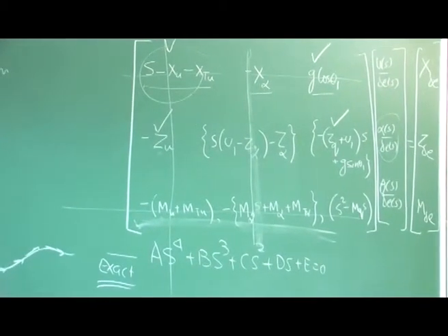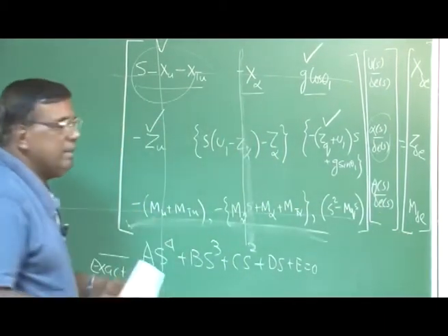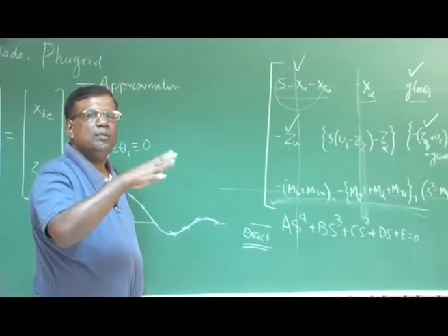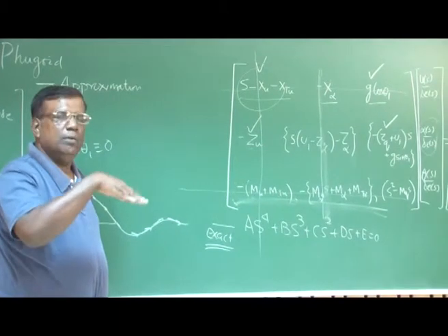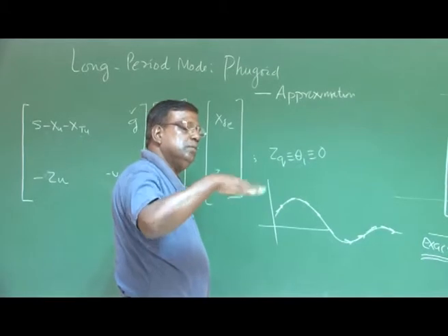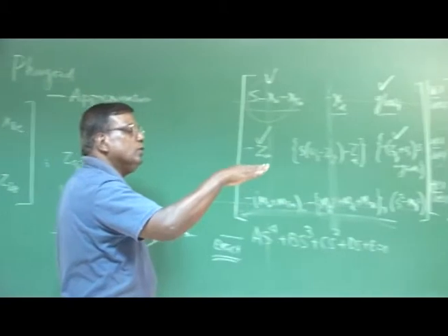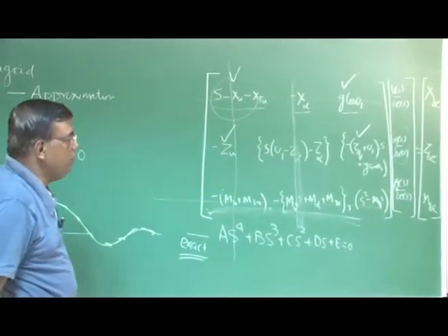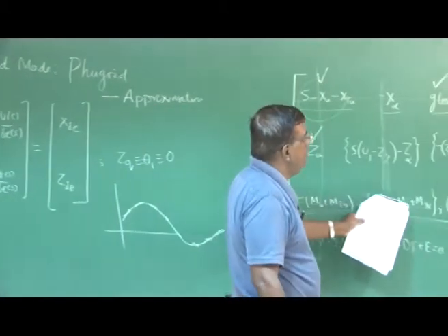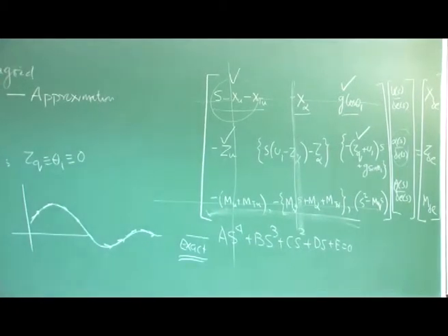Second thing, the third equation, which was here through M delta E, this is basically representing the pitching moment about the y-axis of the airplane. So, this sort of a motion we are talking about, but actually we are approximating the Phugoid mode. This oscillation is not dominating, this is dominating, right. So, not much of moment about the y-axis. So, we are saying this is also superfluous. So, we are deleting that. Okay. This is an approximation.